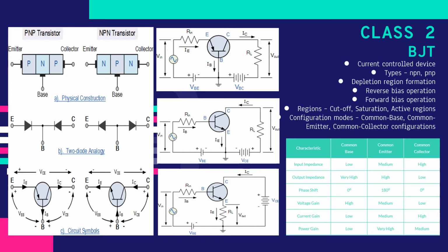This was followed by the reverse bias operation. Reverse bias is where you have the negative end of a battery connected to the p-type and the positive end of a battery connected to the n-type. The electrons in the n-type flow towards the p-type and the holes in the p-type flow towards the n-type. Here the depletion region increases, therefore at some point some holes cannot jump into the other regions, and the same goes for the electrons. And so in this case your current keeps decreasing.